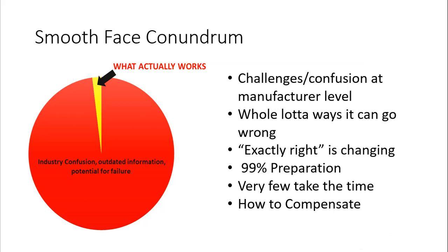Okay, if we get an oil-based penetrating first coat on there, semi-transparent or even a transparent, then in the field you can specify, have a painter come out, sand it, and then put an oil-based penetrating stain that you can actually get aftermarket at the non-manufacturing level. And that's a challenge we can talk about as well. So that's how you would compensate in the spec.